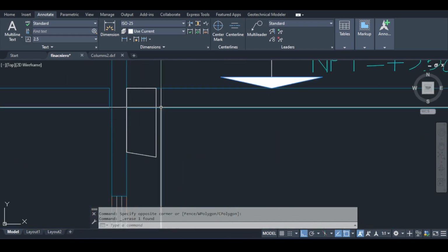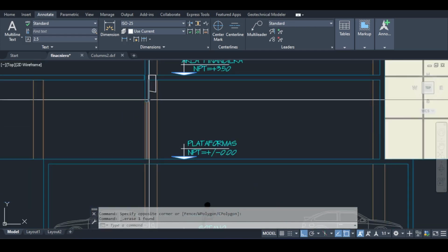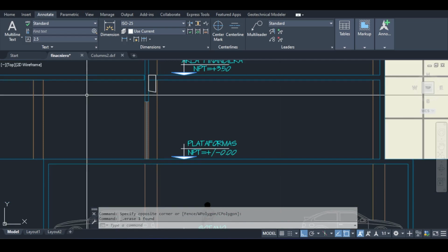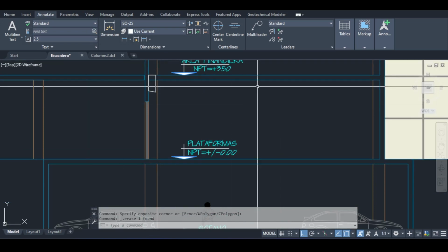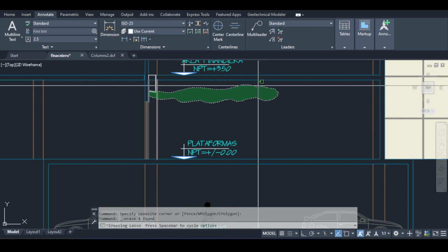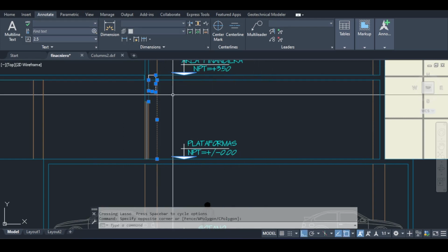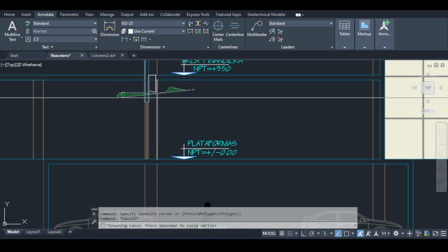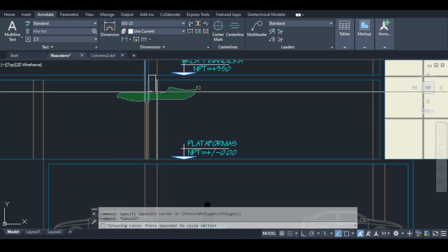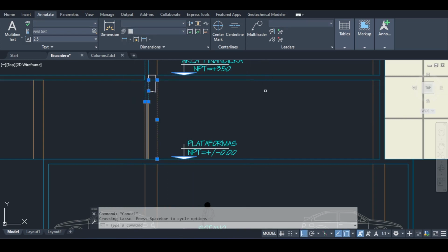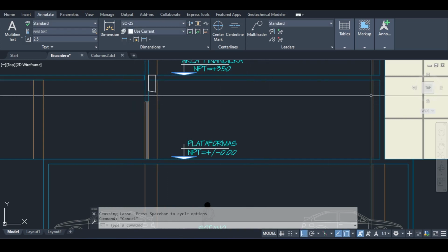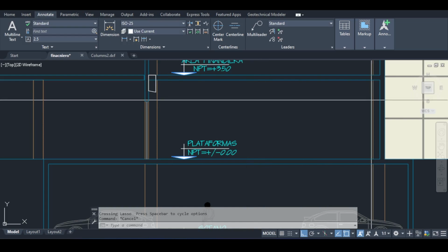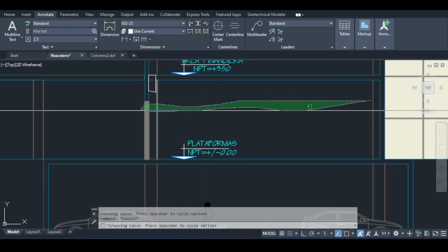Not only this, there is another issue. You see, you sometimes might, if you live in hot areas, you might have central air conditioning flowing through the building. So you have all kinds of mechanical fittings moving here in this region. And those mechanical fittings, if it's a central AC, might need to cross below your beam, further decreasing the available clear height for you. And finally, you might need to cover this by a false ceiling or a gypsum board or something, and the false ceiling itself needs some thickness or some height.